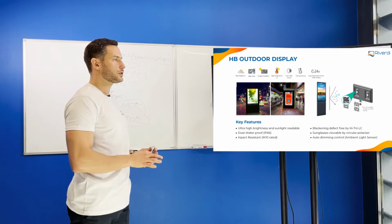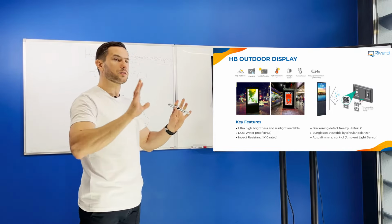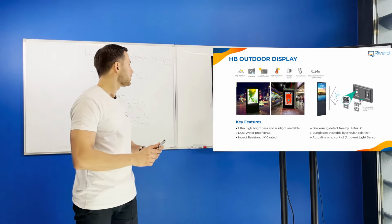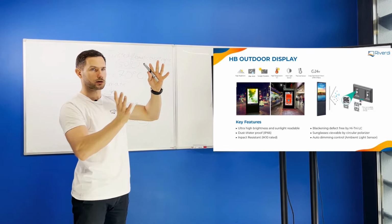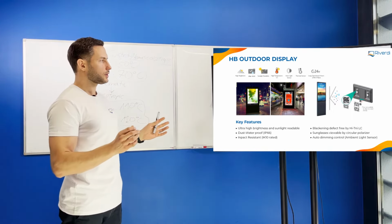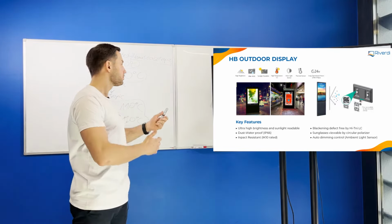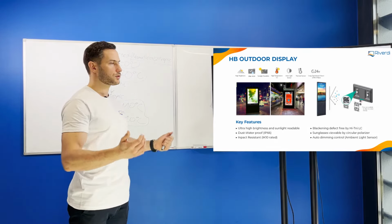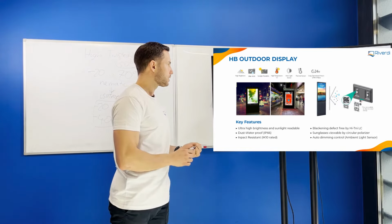Maybe you have seen some displays that are used outdoors, and sometimes they become black. We call it the blackening effect. If the temperature becomes too high, that means the crystals become isotropic, and you can see maybe part of the display is black or the whole display becomes black, depending on temperature. The good thing is that it's not breaking the display, so once the temperature drops, it goes back to the nematic phase and the display works again. But at a high temperature you cannot see anything on a display. It's basically not working.